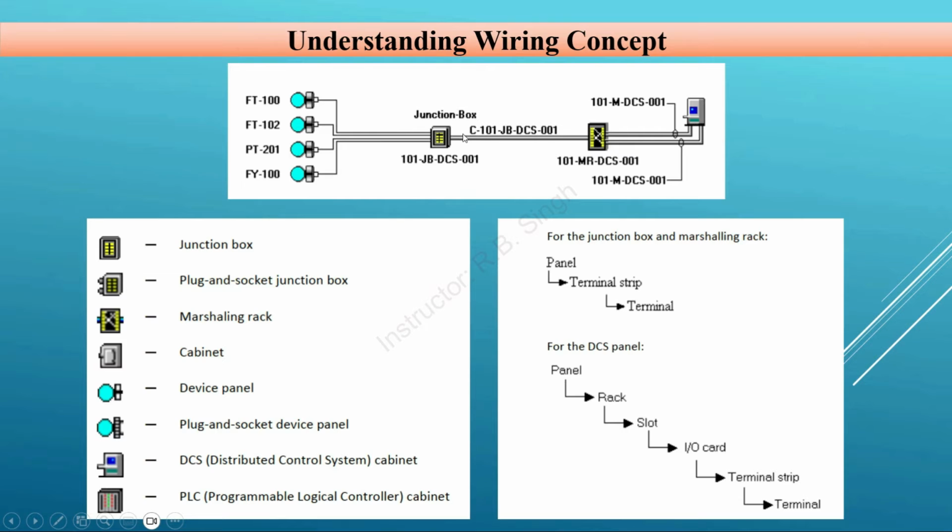Again there will be a cable, which is called a multi-pair cable or main cable. There will be many cables inside this one main cable, and this cable's end two will be connected to the marshalling cabinet, and between the marshalling cabinet and the system cabinet there will also be wiring. This complete wiring we need to do in SPI, and we need to take the report.